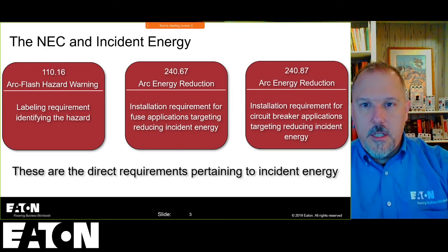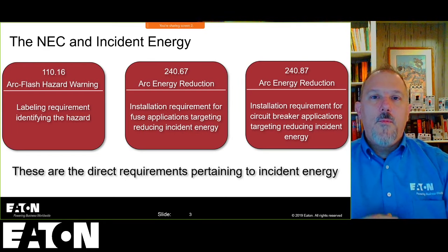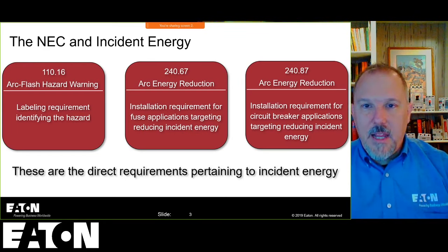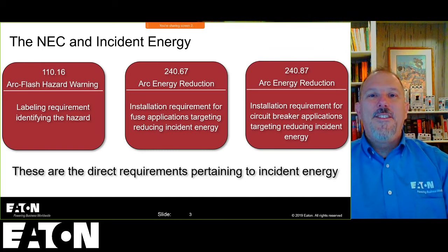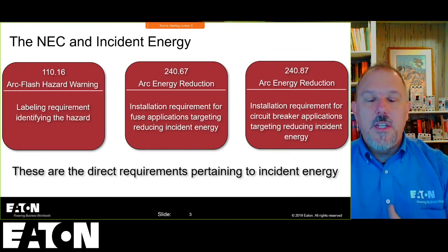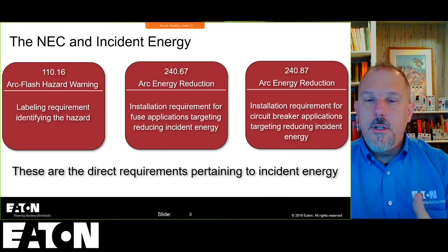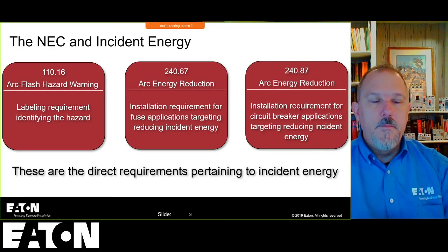That second one's a doozy. So when they grounded the system, they eliminated that free first ground fault, and that first one now is the doozy. So you had more likelihood of problems, because you can't live with one ground fault in the system.